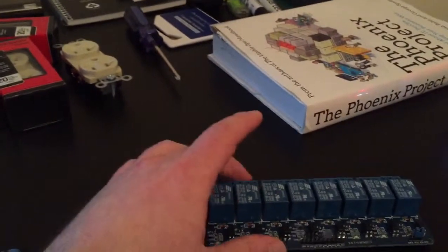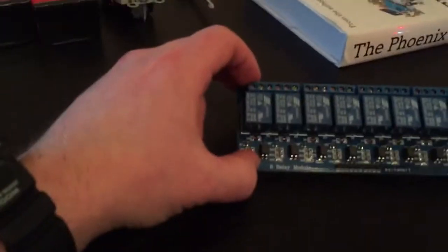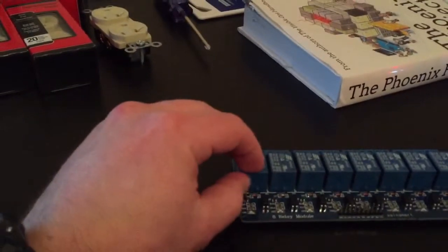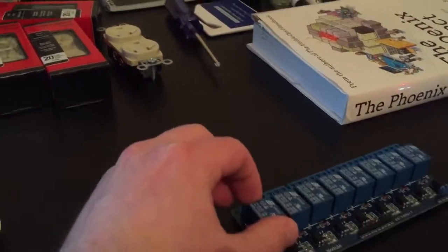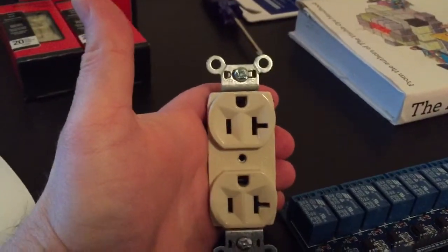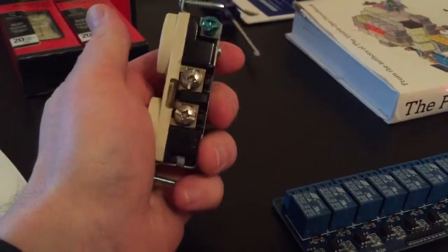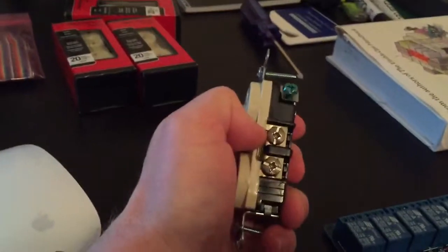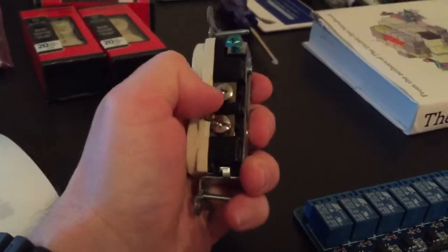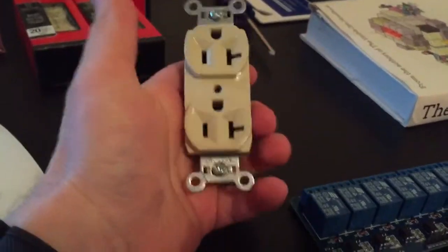Inside, if you actually shake this, you can hear the switch moving back and forth. There's an electromagnetic coil inside, and once you charge it with 5 volts of electricity, it will form an electromagnet, which will then close the circuit. We will eventually wire this up using regular 14 gauge wire in a house, and hook it up to an electrical outlet. We can individually supply power to each socket on this outlet just by breaking this metal strip right here. We only need to do it on the positive side.